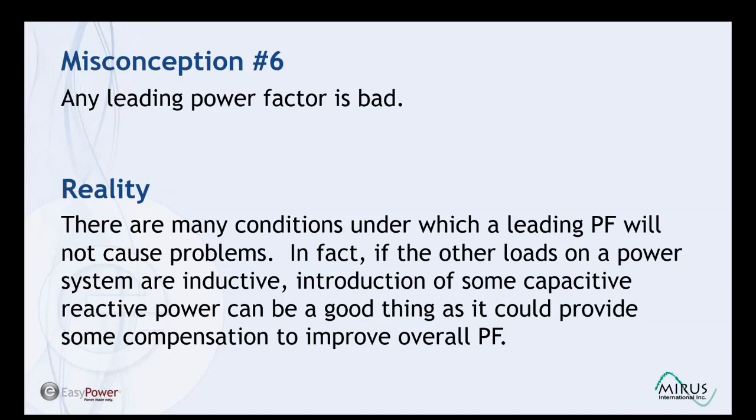And in fact, if other loads in the power system are inductive, the introduction of some capacitive reactive power can be a good thing, as it could provide some compensation to improve overall power factor. So we need to be careful of placing conditions that are too rigid with respect to power factor, which can lead to installations that are more complex, costly, and unreliable than is necessary.